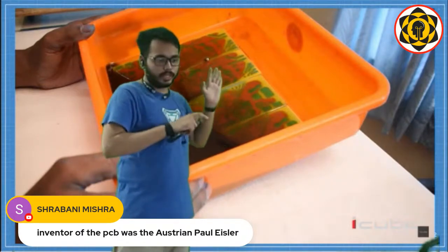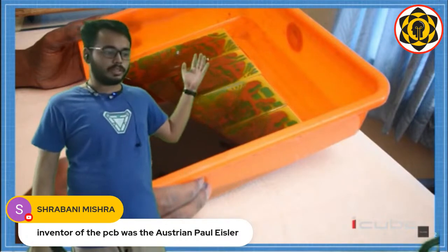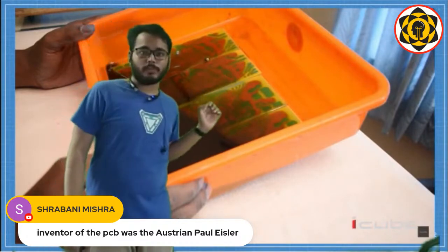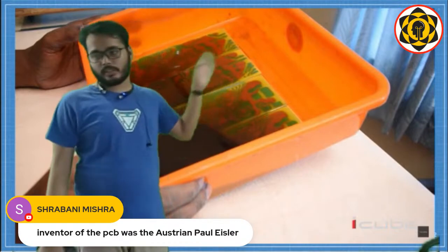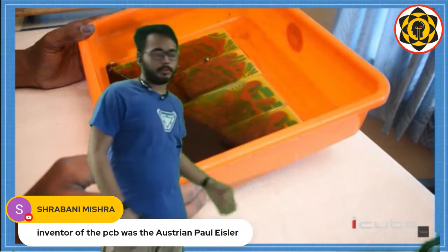Then if you remove your hand, only the part where you put your hand, the pencil marking will be there, right? Same principle. We first put the paint there to cover up the copper, and then we put a solution that eats away the copper. The places where the paint is not there, it will eat away the copper, and then only the fiberglass substrate will be visible.